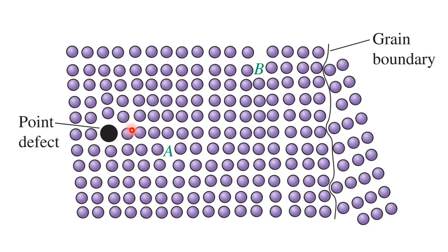And this is exactly what we are doing when we alloy the iron, Fe, with carbon to introduce point defects. These point defects interrupt the dislocation movement, leading to the formation of steel, which has much higher strength than the iron itself.